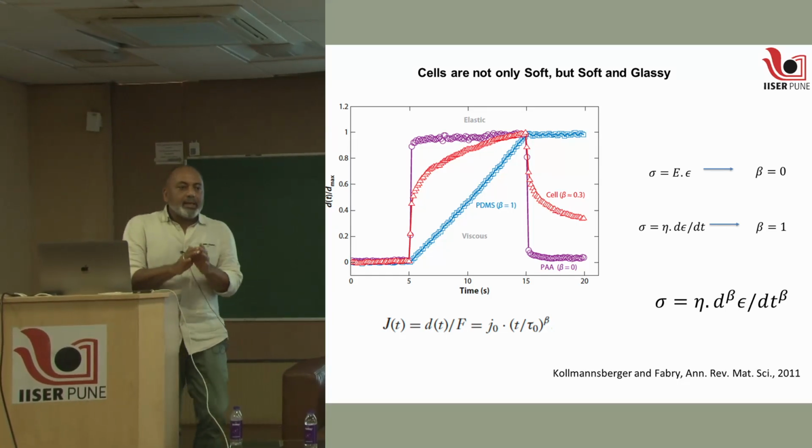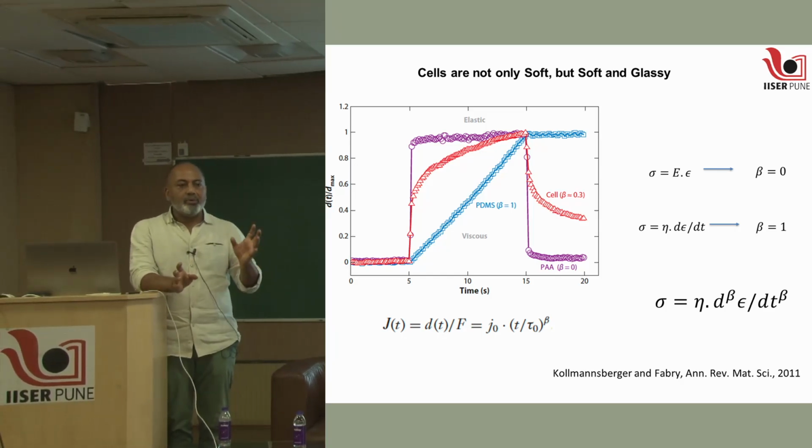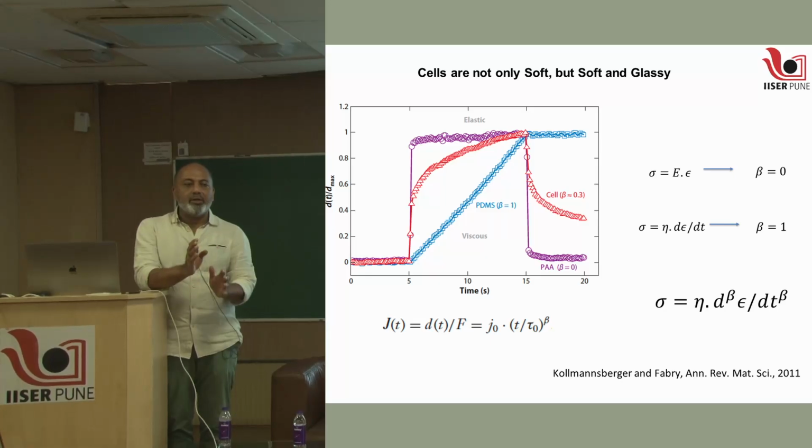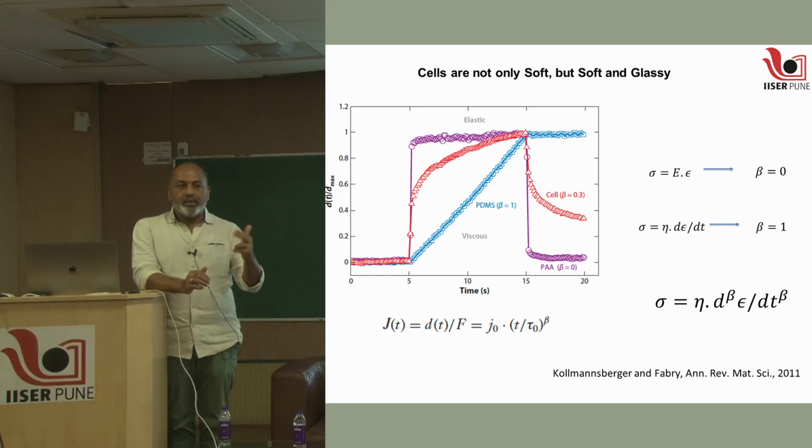Now, how do I then characterize the material, and what is the classification scheme between liquid and solid? We have something in between now, because partly you have an instantaneous response, let's say of this silk thread. That is a Hookean response, and then it starts to extend further, and this takes its own time, and if you take a different type of material it will again extend like that, but that time will be different.